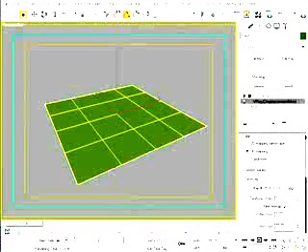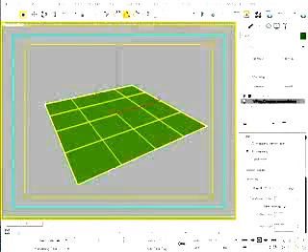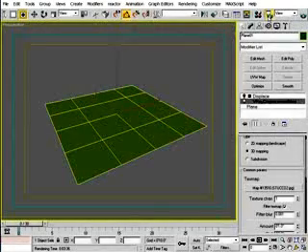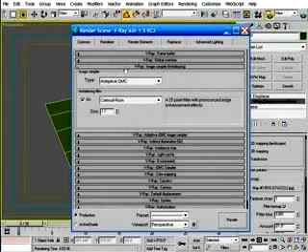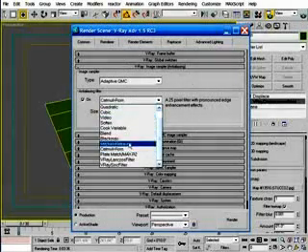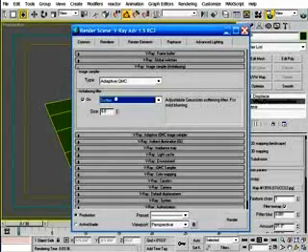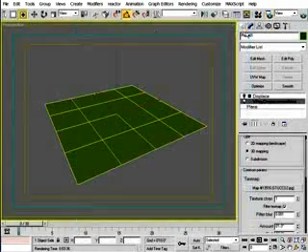One problem you might find when you use the VRay displacement modifier for animations is flickering. This is because of the often high contrast of pixels that usually comes when you use displacement. When using displacements for animations, you might want to pay a little extra consideration to the anti-aliasing filter you use, and you might have to resort to using a more blurry filter than you would normally use, such as the soften filter.